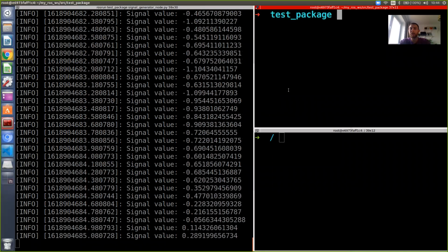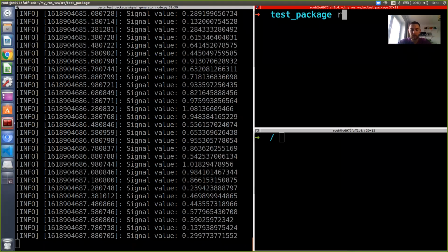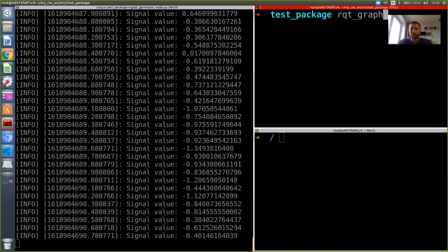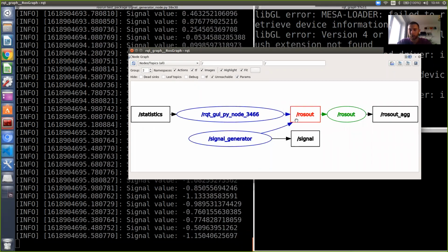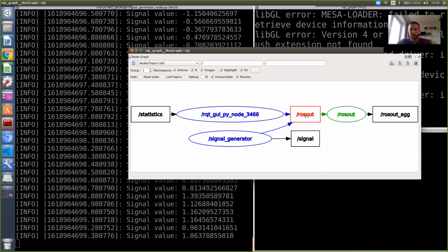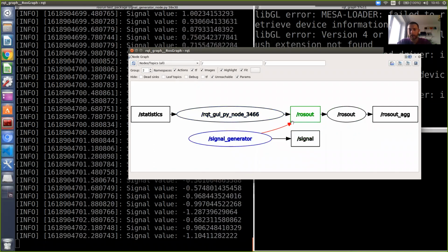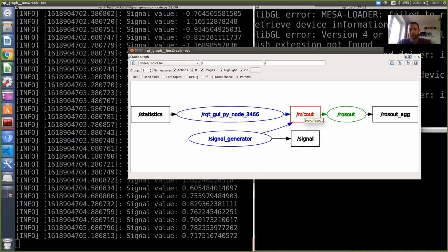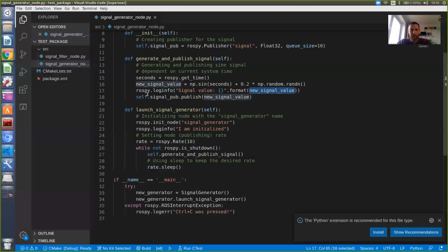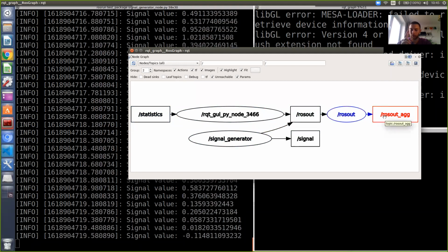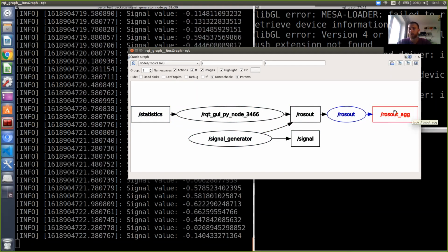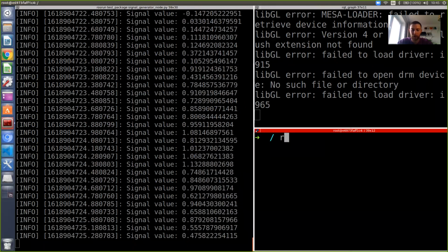But there is more. You remember that we discussed it in the very first ROS lecture. There is a specific debug node which is called rosout, which is launched every time ROS master is launched. And this rosout collects all rosout topics. These prints are going not only to console, but also to this rosout topic. And this node rosout collects them and does two things. First of all, it publishes it to the rosout_agg topic, and we actually can try to see it.